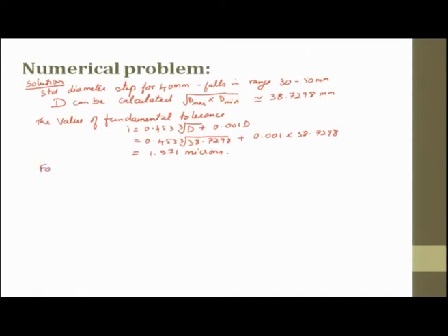Now let us get into the hole quality. What they have said is H8. Okay, H8, the fundamental tolerance is 25i.